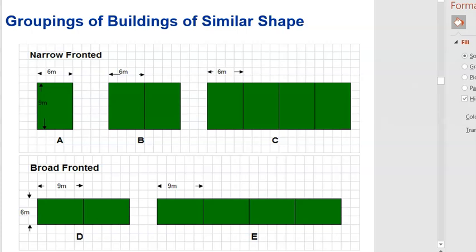So, here's another example of maybe a traditional housing estate. If you were to measure and assess the floor areas and the wall areas of each of these structures, bear in mind that the internal dividing wall, the party wall, does have a cost, but it's not going to have the same cost as the external wall. You're not going to have the same level of insulation, external render, etc. Probably lighter foundations also.